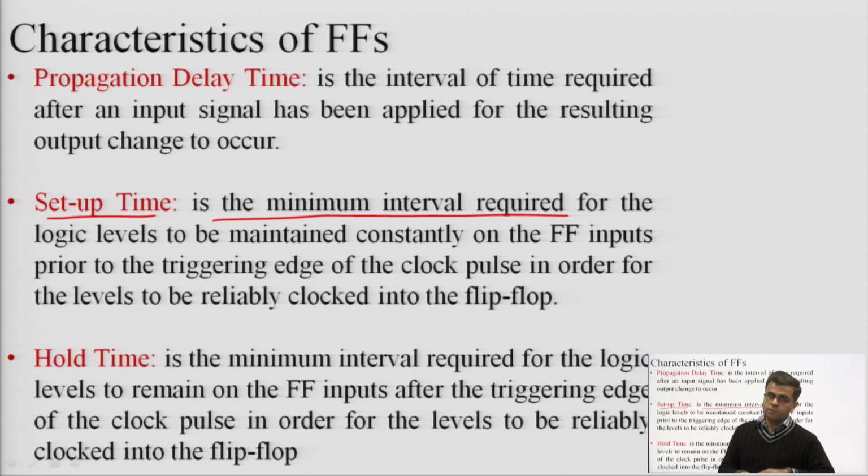So, the time before the clock edge is termed setup time and the time after the clock edge is termed hold time. Both have some minimum values. For that amount of time we have to maintain those inputs, so that these inputs are reliably triggered inside the flip flop. Okay. So, these are the three characteristics.